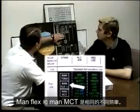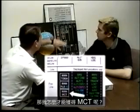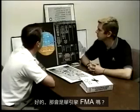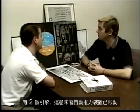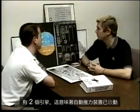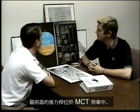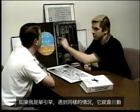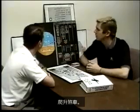MAN FLEX and MAN MCT are the same detent, so how would I get MAN MCT? MAN MCT is only in flight. Okay. Would that be a single engine FMA? No, it's 2 engines, and it means that the auto thrust is armed and the most forward thrust lever is in the MCT detent. If I were single engine and I had that same situation, it'd be engaged because the engagement range changes to the MCT detent instead of the climb detent.